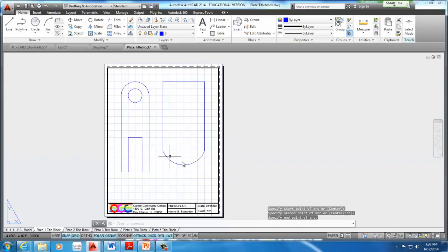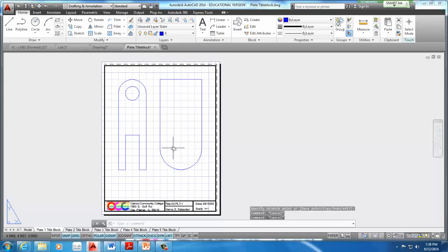Technically, that's not the center point, but that is the arc. Now that looks like it's a little too short. It should have been here instead of here. What we remember from our previous classes, we can select the line. Using these blue points, we can stretch it out if we need to. Some of them move the objects, others stretch. When it's on the line, it actually stretches. So we select that center point, we move it down 1 box, which stretches it down and creates the perfect arc that we're looking for.